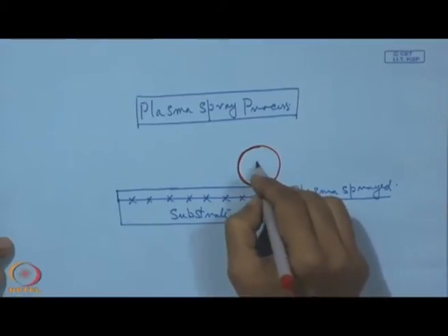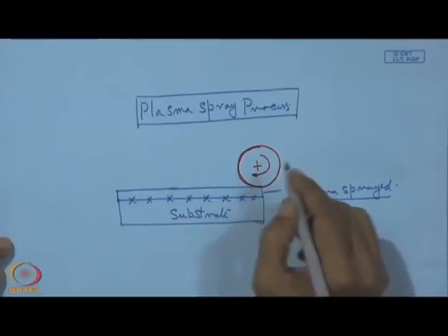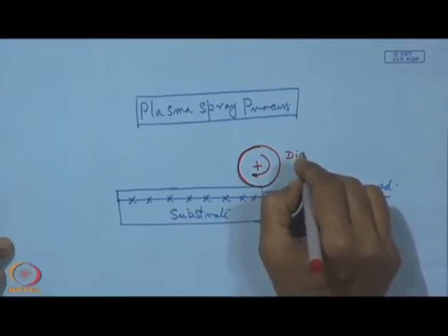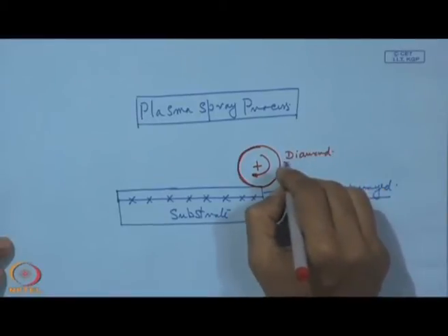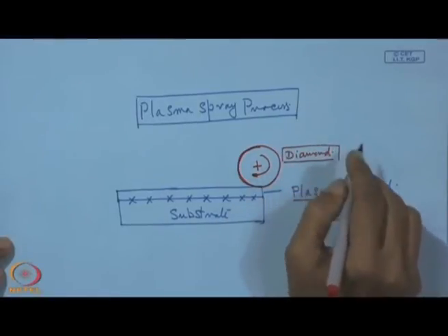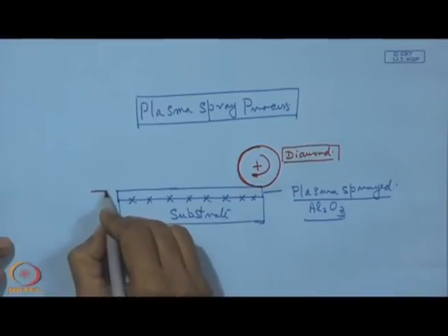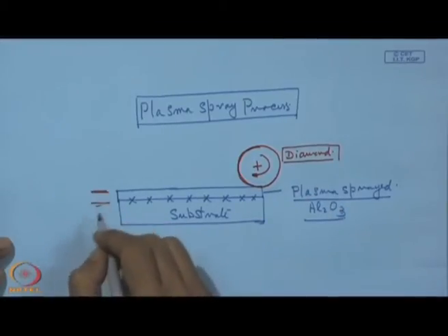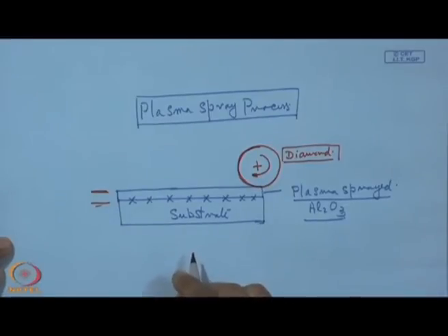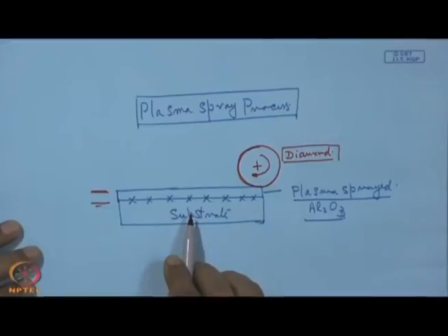and this grinding wheel is made of diamond, it is a fine grained diamond, and with this grinding wheel we can grind, say, a thick layer, and these are the materials which are not for micron level deposition, but it is actually in the millimeter level deposition. 5-6 millimeter deposition is quite a routine thing, so that it can serve as a wear resistant coating and also as a thermal barrier shield.